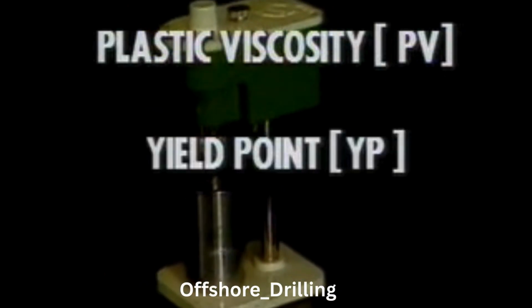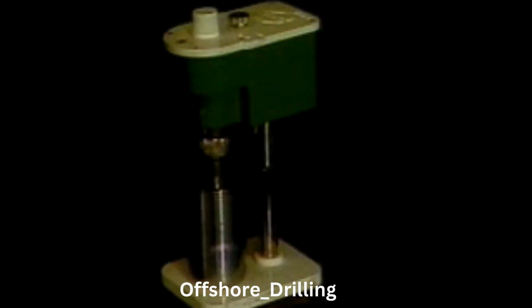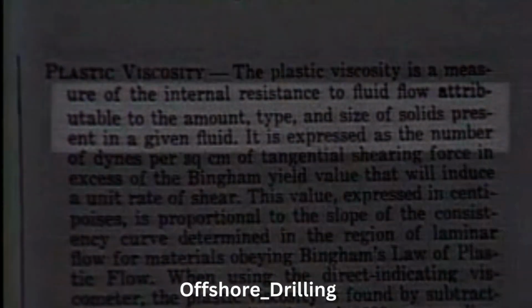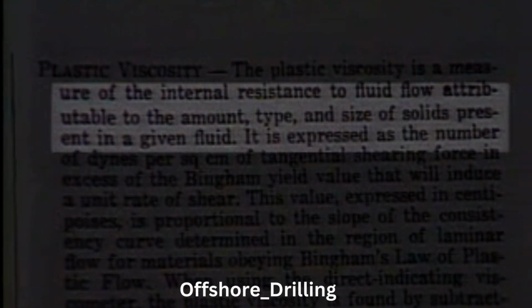When he measures viscosity, he uses a fan VG meter, and he's really measuring several different things: plastic viscosity, yield point, and gel strength. These terms probably don't mean much to you right off, so let's talk about what they are exactly. We'll start with plastic viscosity. The dictionary definition for plastic viscosity is a fluid's internal resistance to flow due to mechanical friction between individual solid particles. What this really means is that plastic viscosity is the measurement of the ability of a liquid, in this case mud, to flow.